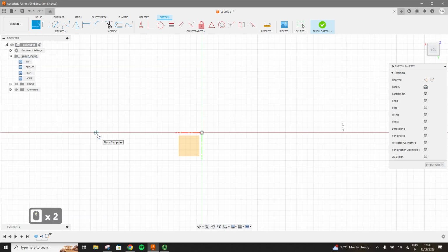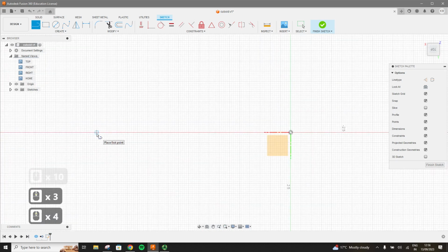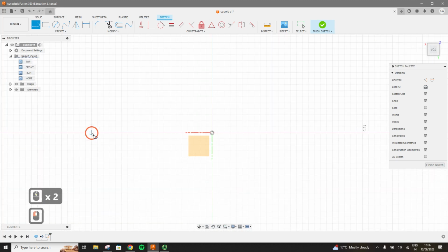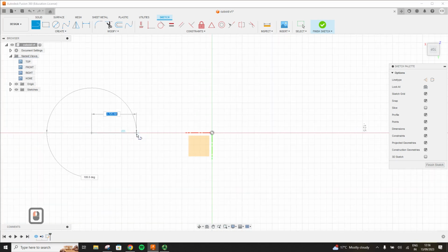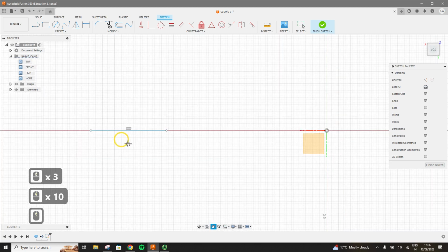So it will allow you to snap to a particular point, which is really helpful sometimes when you don't really want to measure everything. But let's just draw a random size for now. I'm not even looking at the dimensions. So I've clicked on that, and it is like a sticky command. It's just stuck to our cursor. So let's just press escape and let's zoom into our line. Okay, let's see what has happened.